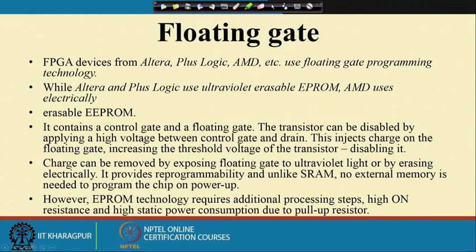This floating gate charge can be removed by exposing the floating gate to ultraviolet light or by erasing it electrically. It provides reprogrammability, and unlike SRAM, no external memory is needed to program the chip on power up.